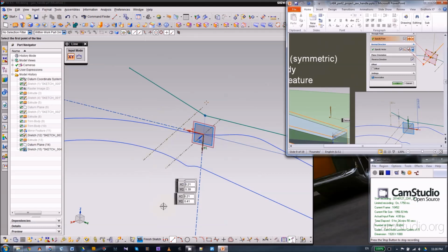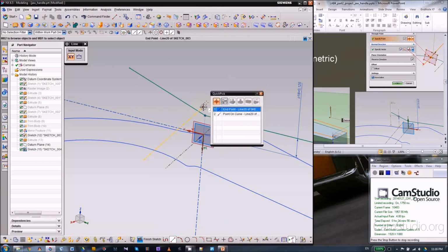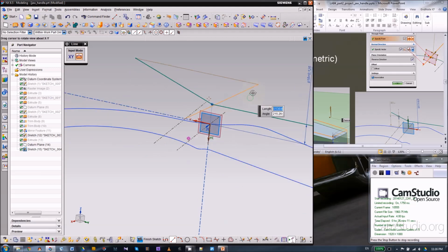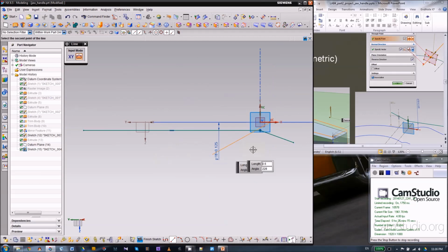So first we will need a straight line that goes up, a reference line. We can snap to this point, which will start that line like this. You might say, why is it here instead of there? That's out of our sketch. Remember, our sketch is only a plane. And if you look straight on, Shift F8.